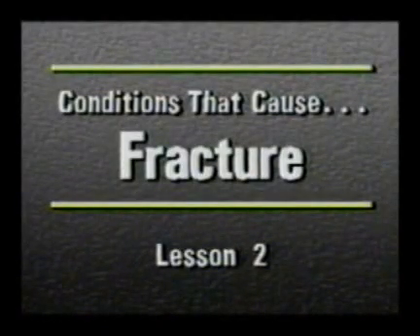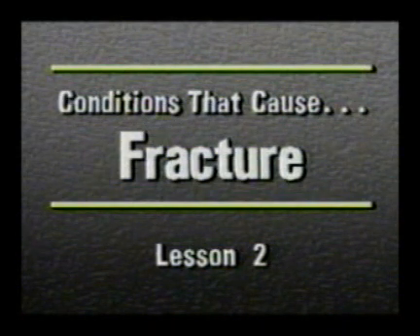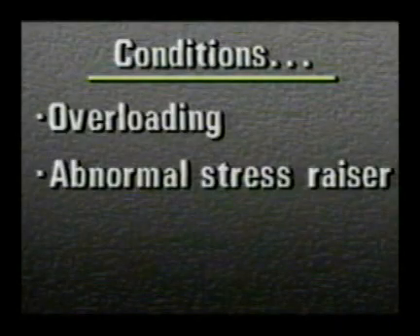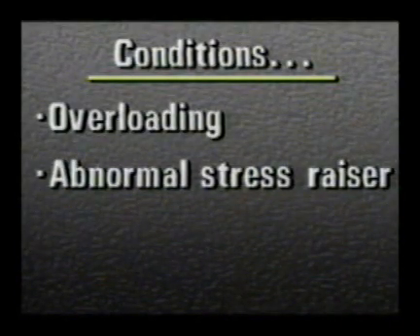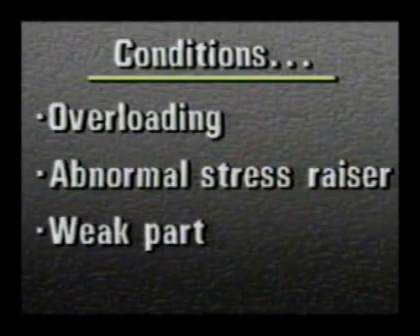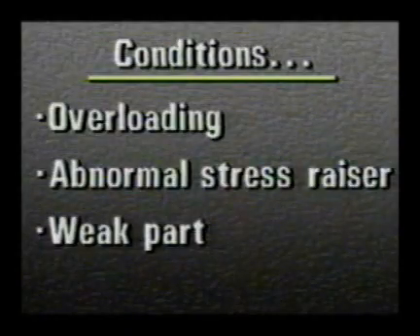In Lesson 1, we reviewed load types, stress distribution, stress raisers, and load rates. In this lesson, we'll discuss conditions that cause parts to fracture. We will discuss 3 general conditions that cause fractures: overloading a good part, normal loading with abnormal stress raisers present, normal loading of a weak part. In this lesson, we will learn to recognize the differences between normal and abnormal conditions.